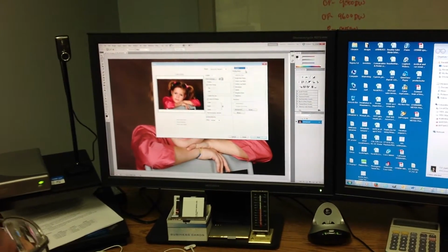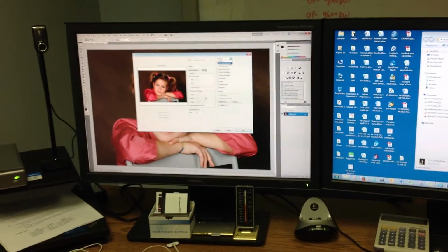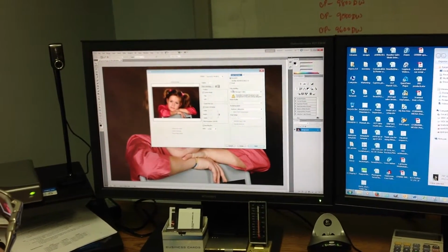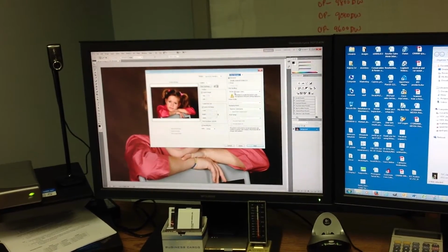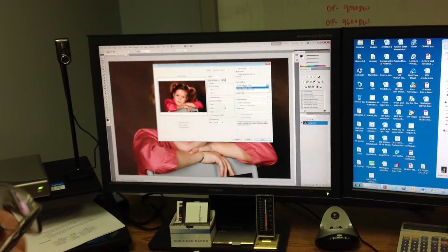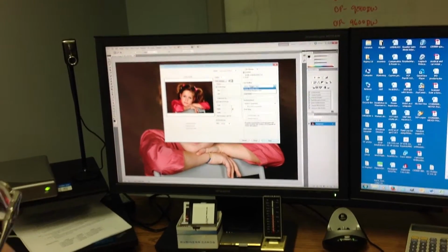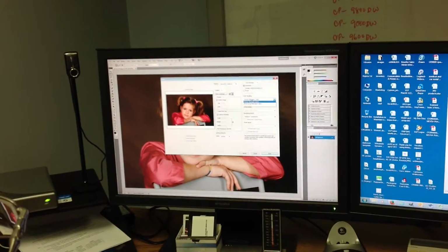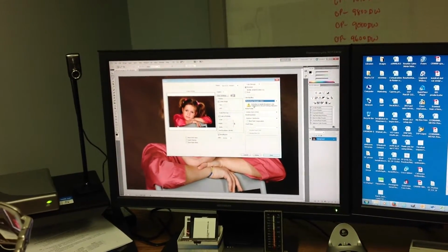Output means use the printer driver, but in most cases they use color management, and it says color handling here. This color handling is: do you want me to handle it by the printer or by Photoshop? So that's your preference. In either case, you still have to use the same profile we provided, which you have downloaded and installed.